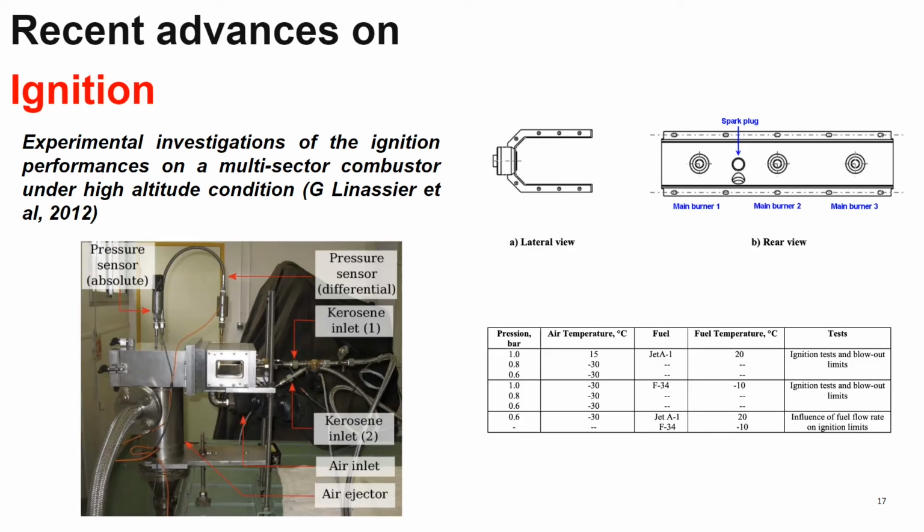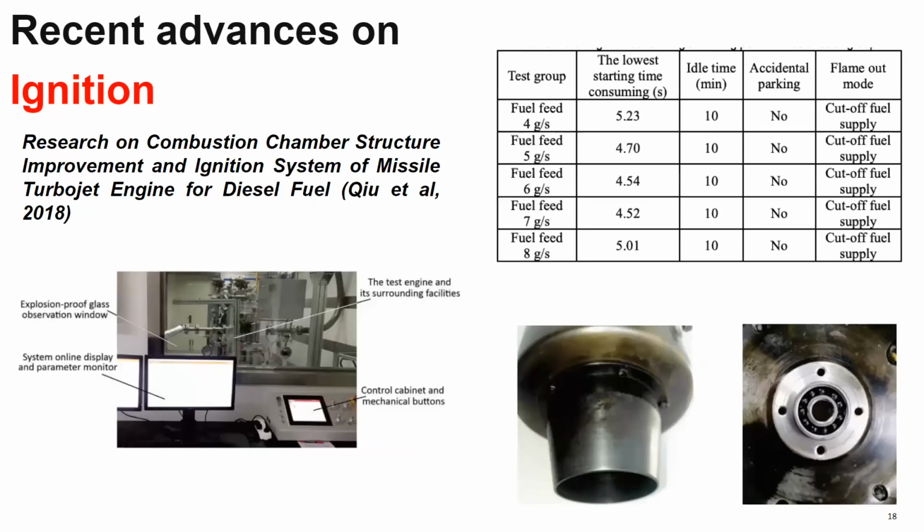Both main burner ignition sequence and starting injector ignition performance have been tested against those of full annular combustors. Future research should incorporate interferential filtering and enhance high-speed cameras to enhance flame visualization, particularly for flame propagation between burners. In order to describe the flow structure inside the combustor, optical diagnostics like PIV or LDA should be investigated.